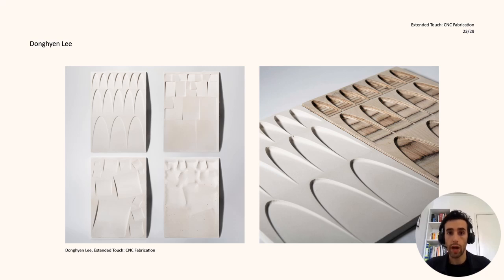We also demonstrated how a low temperature oven ensures best practice for water evacuation and structural stability after releasing the relief from the molds. These examples by Dongyi and Lee show the intricacy of the geometry you can achieve with making molds in CNC fabrication, but it is very important to employ best practice principles when you dry your plaster casts.